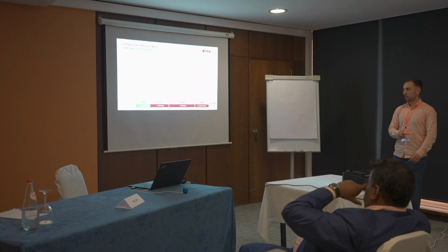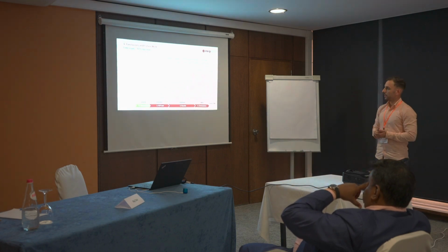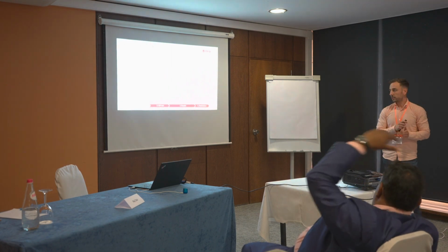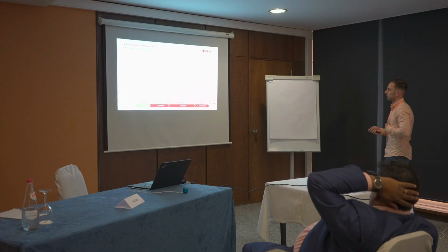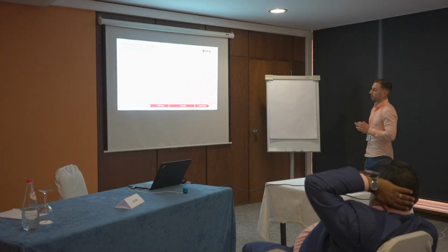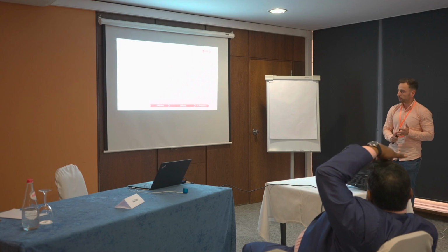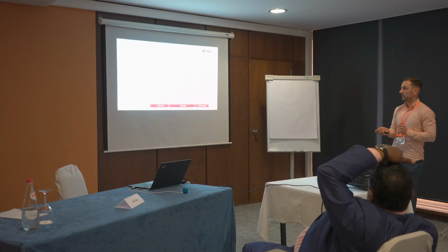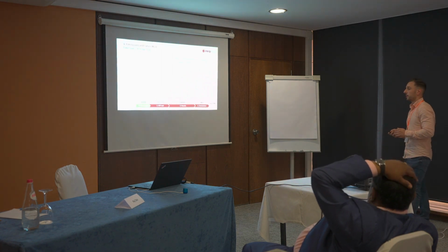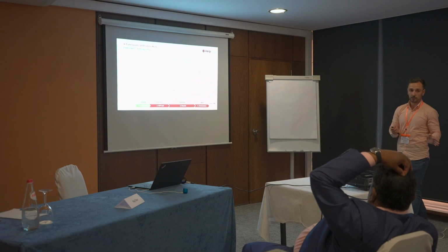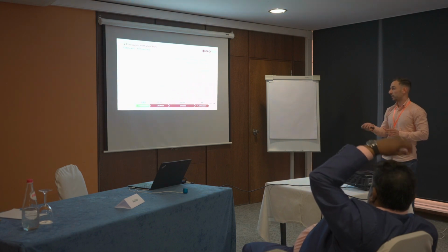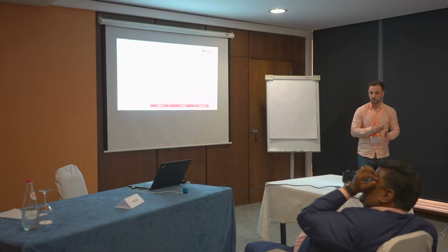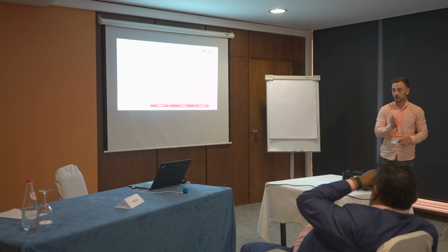So, in order to conclude, we are studying M3 vehicles according to Regulation 29, which tests the vehicle in a frontal collision. We performed numerical and experimental tests, and we observed a high resemblance between the experimental data and the FEM. Okay, a good agreement between experimental data and FEM data. There was a clear visualization of the impactor torsion that was very difficult to achieve in FEM simulation.